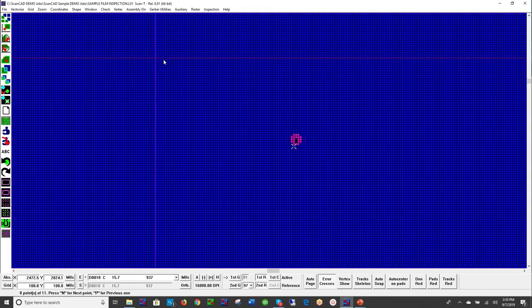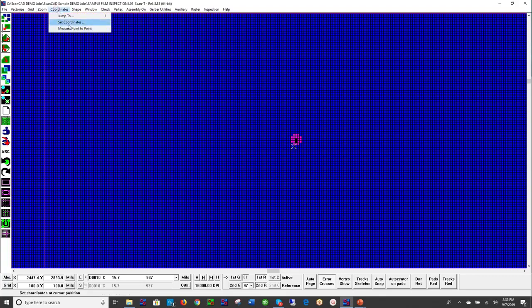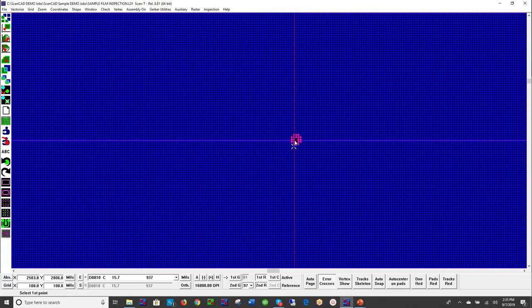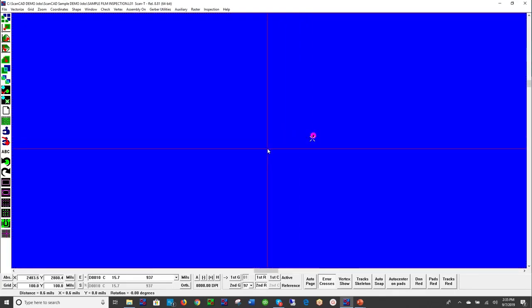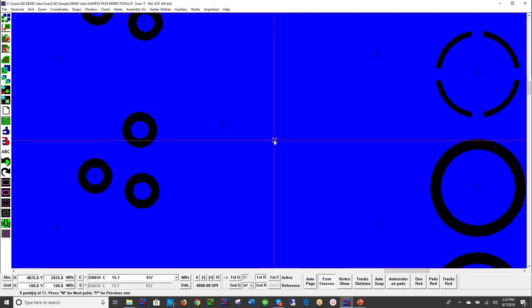In fact, I'll just measure this pinhole. Remember, we have measurement capability. I can measure this pinhole, and we can see this pinhole is 0.6 mils. This is approximately 13 micron. This is a 13 micron pinhole in the board, okay?